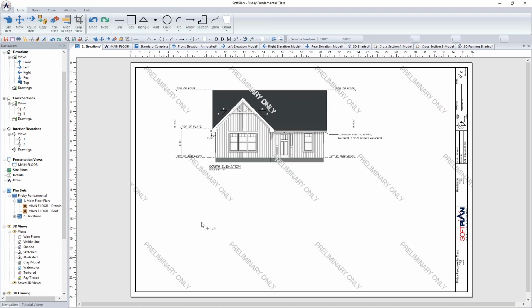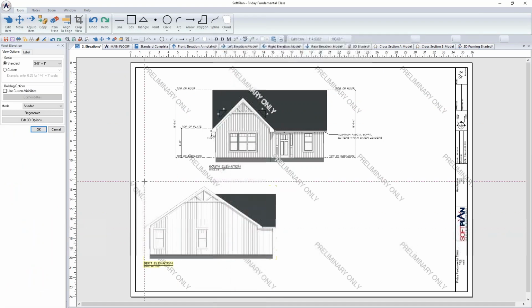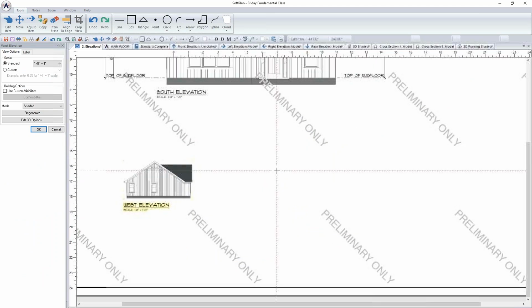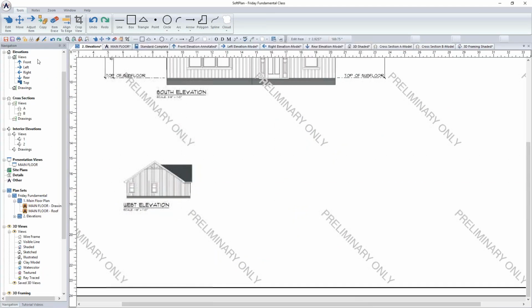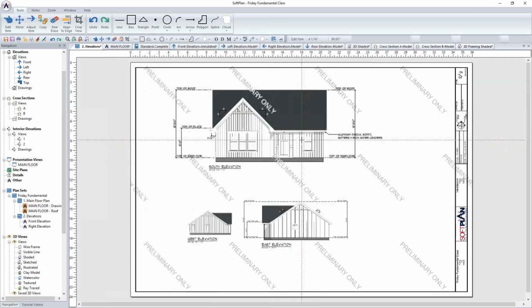So in this case here, the left elevation, I'll leave it in model mode, and as I do, you'll see that it's sans that. But you can always edit this, and change things like what the scale is going to be, etc., for the drawing itself. Okay, so in this case, I've actually scaled it down. So that's going to be your difference on whether or not you want to, as you're dragging your elevations in, if I go to the annotated, it's going to pull my dimensions off. The model is where you're going to do edits and modifications for that, okay? And you can then move these things around, per se, on your actual drawing.